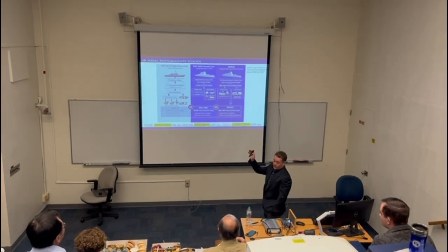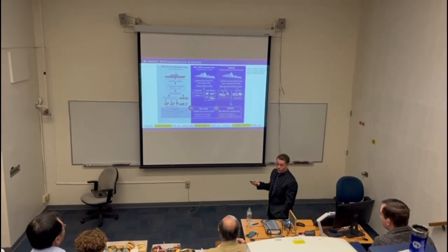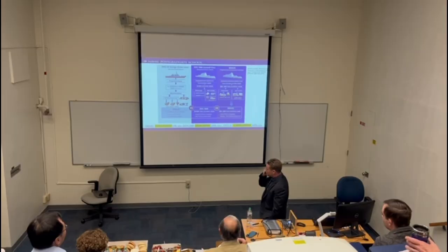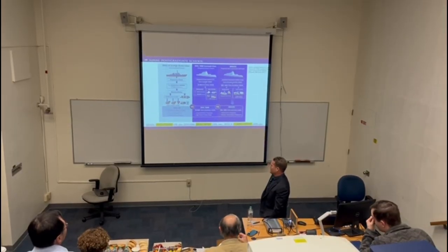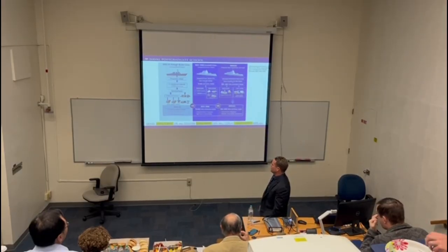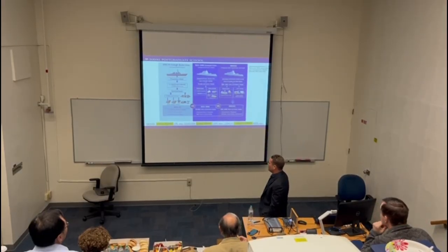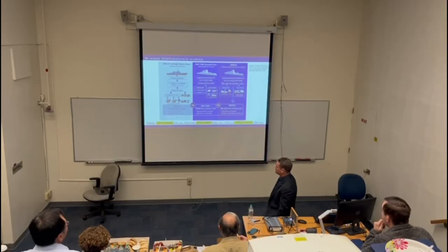So how does this really apply also to our field in the Navy, more specifically some of the DDGs here? If you look at 1991, 10% of that ship was actually electrical, right? So you had 75 megawatts, but only 7.5 of it was actually electrical. Anything that's electrical can put off EMI.